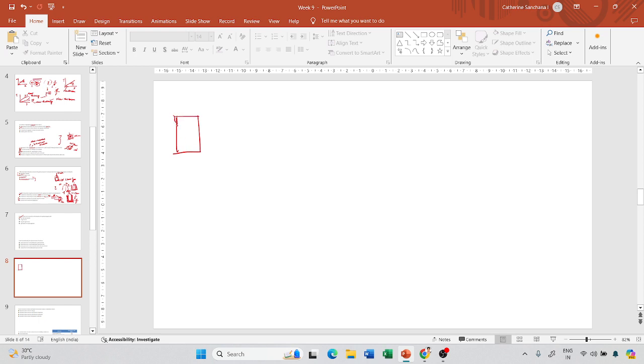So you have a cylindrical sample. Now we saw that it has to capture the influence of frequency and temperature. So I need to first carry out the experiment at different temperatures. Okay, and I also should carry out the experiment at different frequencies. Why? Because I have to identify the influence of temperature and frequency on the modulus of the bituminous mixture.